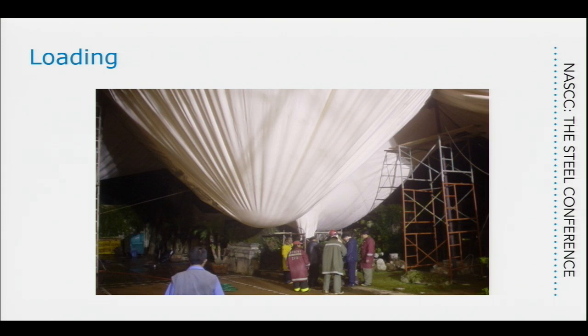That makes me think of what is the service life on these materials, and also is there a creep and relaxation that you have to worry about as well? Yes, there's a creep that happens, and we consider some of it, but because they're very elastic, it's not as much as you would think. There's a very small factor of relaxation in this, especially because the relaxation comes a lot into play when you're losing that apparent modulus of elasticity.